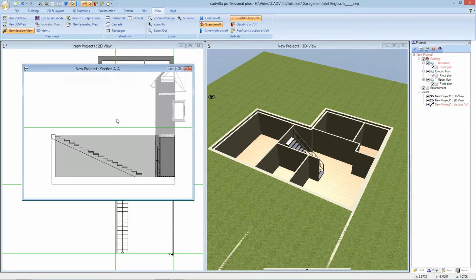and before we enter now the extrude solid, we switch to the layer environment, because we will create the extrude solid on the layer environment. Therefore, we press Ctrl and we select the layer environment with a left mouse click.